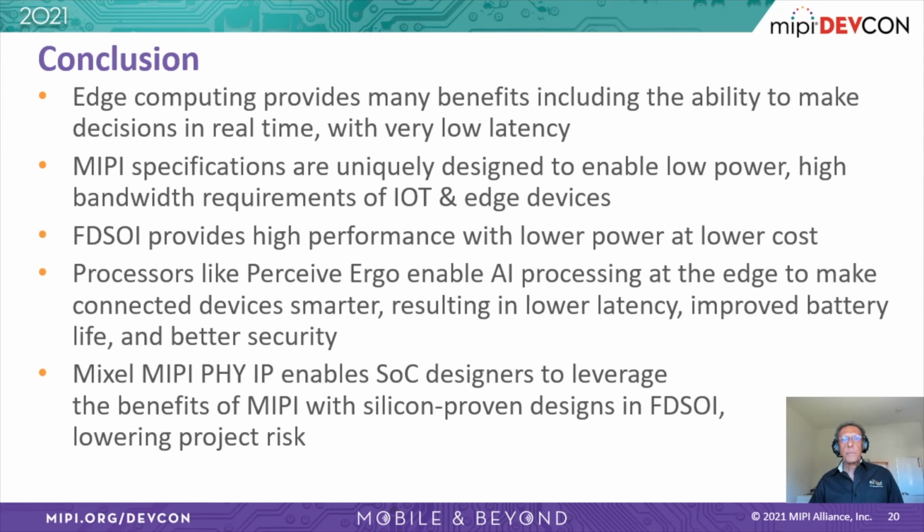Let us now conclude by summarizing the presentation. Edge computing provides many benefits, including the ability to make decisions in real time with very low latency. MIPI specifications were uniquely developed to support low power, high bandwidth applications for mobile and edge devices. FDSOI is well suited for high performance applications at lower power and cost compared to FinFET technologies. That makes MIPI specifications and FDSOI technologies a great match for edge devices.